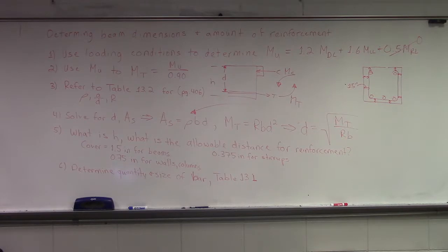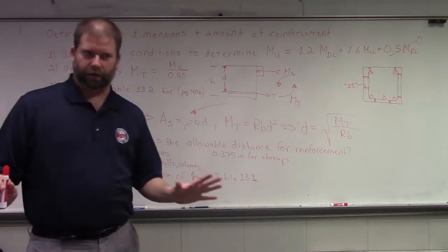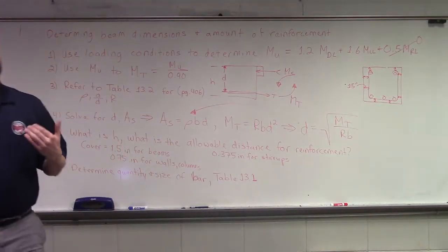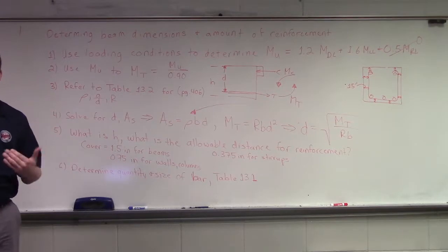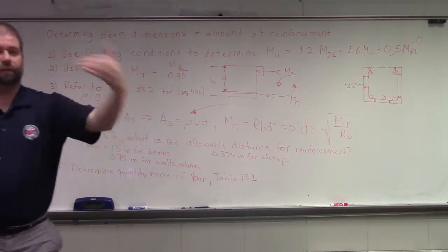And are you giving us the size, or do we just assume our aggregate's 3/8? For the purpose of this, we're not gonna complicate things with the size of aggregates of the concrete. But how this works in the real world is, keep in mind, the spacing is given to the ready mix producer.